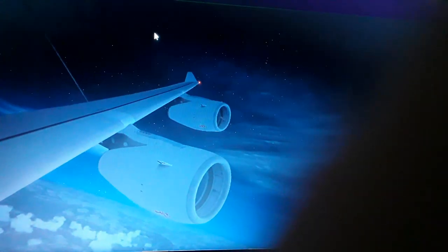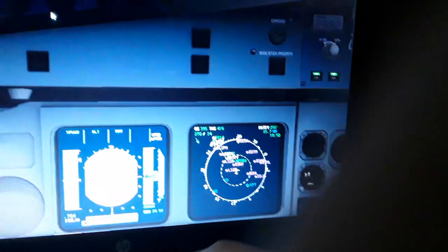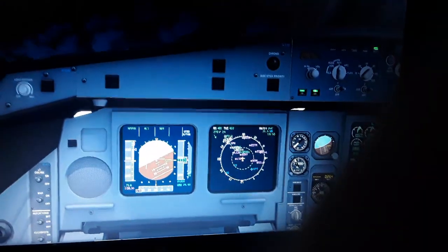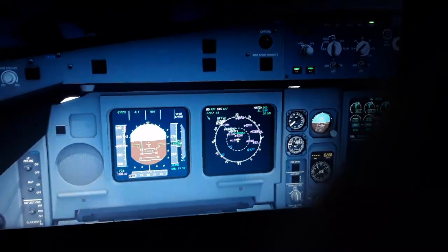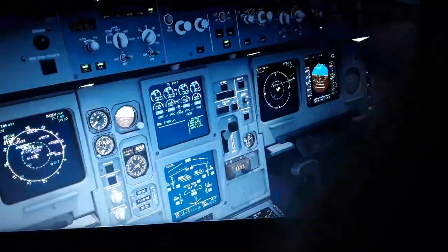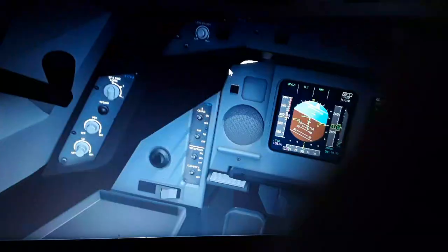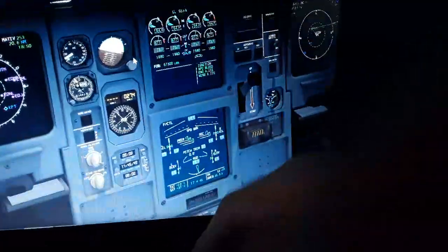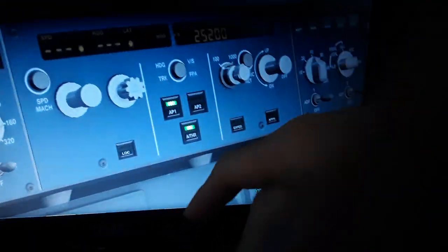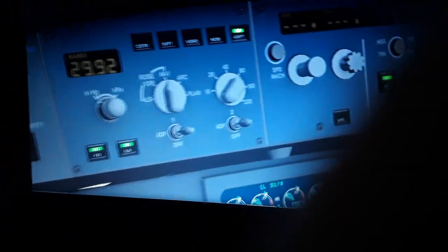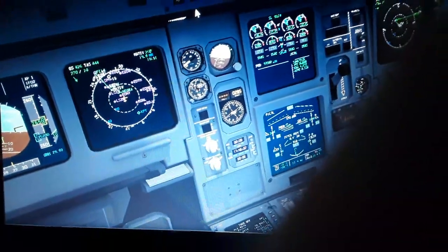It's 7,000 feet, leveling down now, going lower actually. Maybe use the autopilot mode now, just to show you how to connect the autopilot. So we turn this green switch here, we turn this off to on, autopilot 1 or autopilot 2, whichever we like, so it's active. So maybe we have to turn the others off, not confuse the autopilot with the other system.